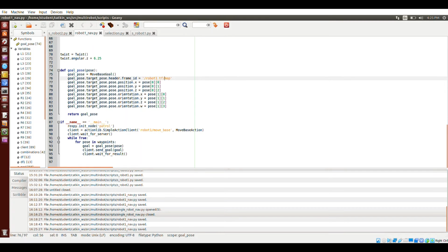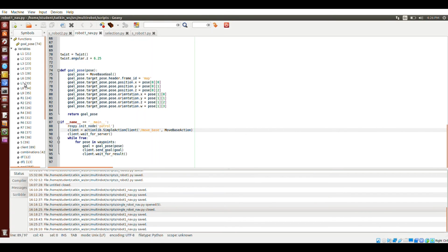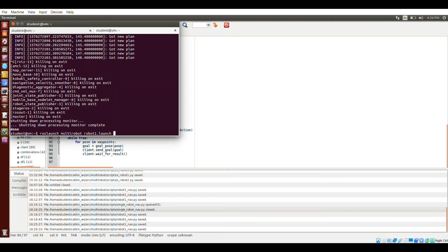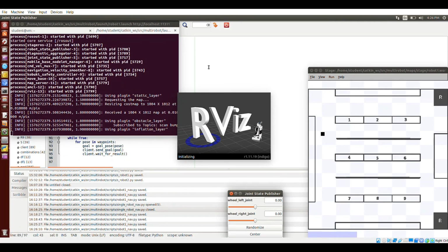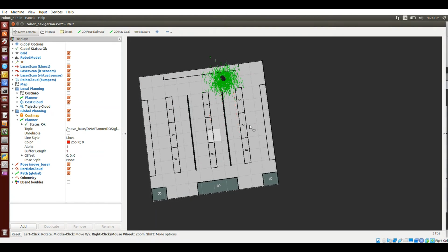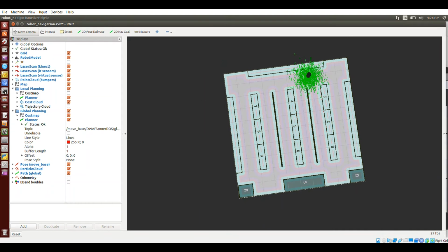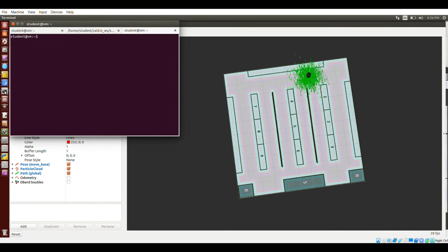So now jumping back to the part 1 scenario in which we saw the 2 robot navigation, but it wasn't as clear because the Ubuntu machine was so slow. So now I'm going to show you the same operation but with only one launch file and one robot. Before we go further, we need to remove the remapping parts from the navigation file. It can be done by removing the robot 1 and robot 1 here. Now in the terminal window, open the single robot launch file. It will fire up the RViz. Now position that, and in the new terminal let's run the script we edited.